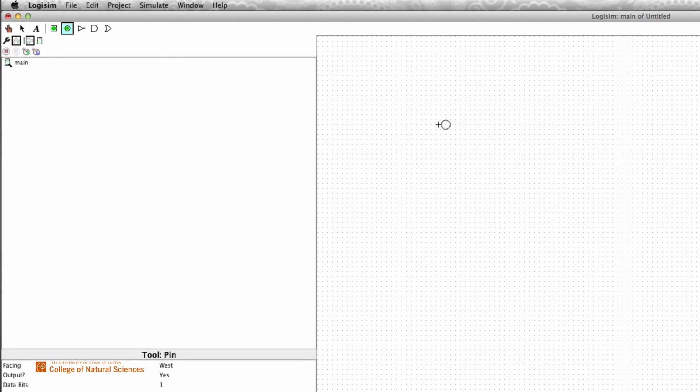Recall that's P and not Q or R. I will start by just putting the NOT right here and I will hook it up to an input, and I will call that input Q. I will take the output of that and I want to push that through an AND gate with P. So pull out the signal right here, put an input right there, and label that one P. So what's coming out now from this AND gate is P and not Q. Good.